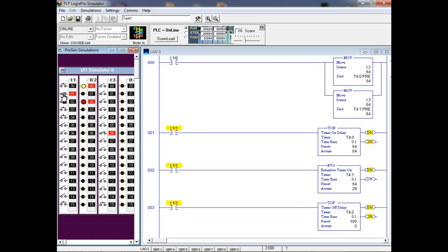So when will we use off delay timers? When do you run into off delay timers in real life? Do you ever run into them? Cars, I have all kinds of off delay timers on your car, right? So when I open my door, my headlights come on. When I close my door, what happens? Starts timing, right? Turns that off. You run into off delay timers a lot, right? So in real life, you can understand why we need these.